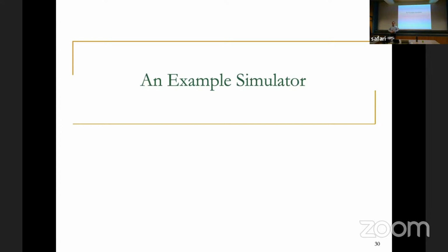So that's a good question. So you can model the functional aspects of memory controller. Yes, certainly. Like, does it obey the DRAM standard, right? Because there's some specification, and you model your simulator in a functional way such that it perfectly matches the specification without any timing information, right? You ignore all the timings. You just look at the functional aspects. Yeah, you can do that, certainly. You can do that with anything as long as it matches the specification. But DRAM control is a bit interesting because the specification includes timing in that particular case, yeah. So I would say that's a bit harder to do.